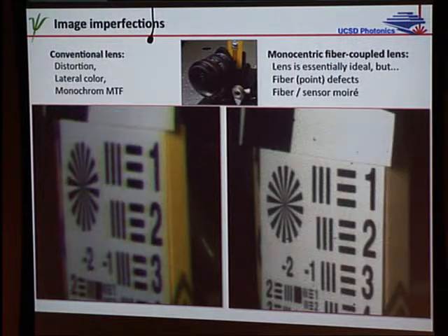If you zoom in enough, you're going to see a couple of things happening. These are the effects of fiber coupling. These are not dead fibers, but fused fibers. When the fibers fuse, more light gets into the cladding, it tends to attenuate, about 50%. But in general terms, this is a much higher resolution than that, despite the size. So this is an exciting sort of first indicator. But we got to go further.